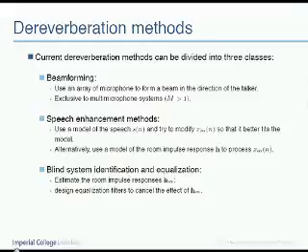So I believe, at least from my thesis work, that you can divide the current existing dereverberation algorithms into three large classes. One is beamforming, where you have some kind of array of microphones and you try and form a beam towards your desired speaker, the source, and exclude any other interfering sources. And this is exclusive to multiple microphones.